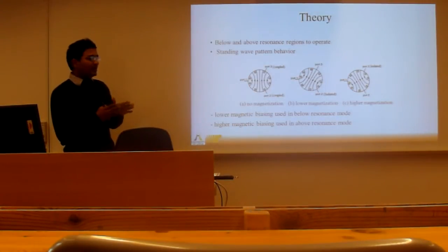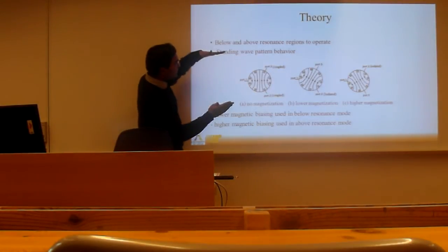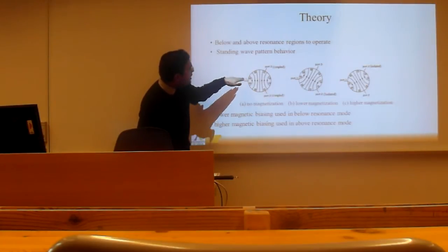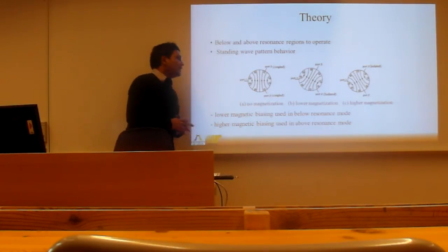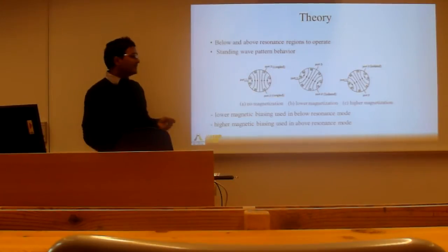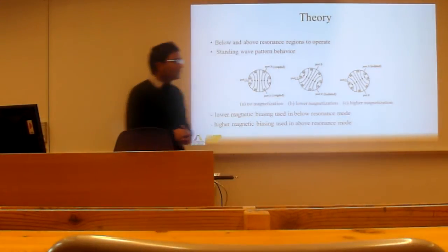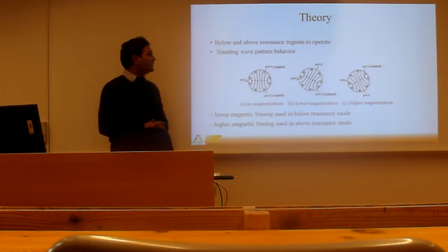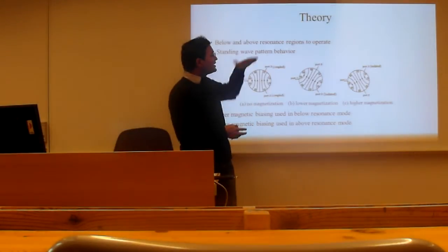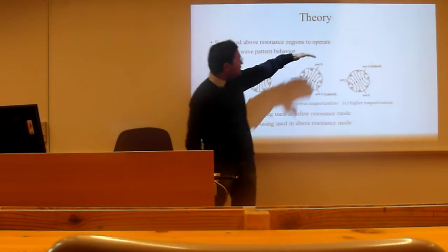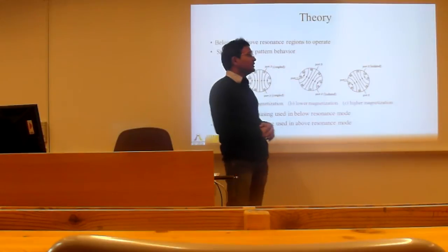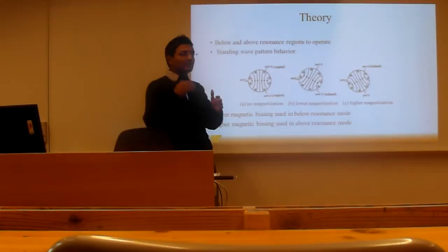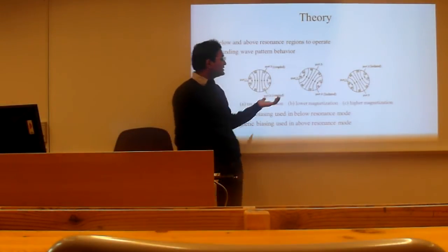When you apply a signal, it will be divided equally: half will transfer to port 3 and half will transfer to port 2. Once you start applying a certain magnetic field, in the second case, the velocities of these two circularly polarized waves will not be the same anymore. One wave will come in phase with the other wave, and both will be coupled at one port and cancelled at the other port. So the circulation occurs in a clockwise direction if you apply a certain magnetic field at this operating frequency range.